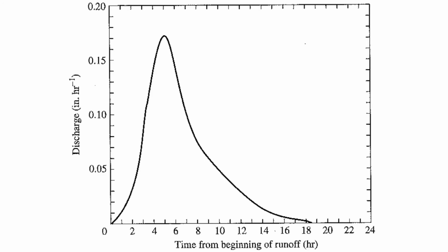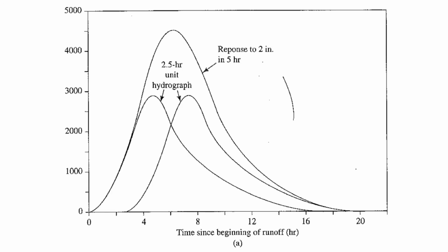We divide the hydrograph by its total volume, and we obtain the hydrograph for a unitary volume of rainfall and for a given duration of the rainfall event. As we have said, the unit hydrograph is only valid for an event of a given duration. However, further hydrographs may be derived.